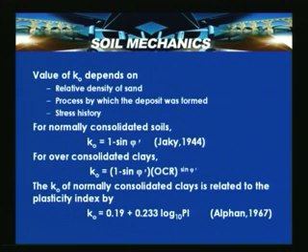For over consolidated clays, K naught is equal to 1 minus sin phi dash into OCR raised to sin phi dash. The K naught of normally consolidated clays is related to the plasticity index. According to Alpan 1967, we can give a correlation between K naught and PI: K naught is equal to 0.19 plus 0.233 log to the base 10 of plasticity index.